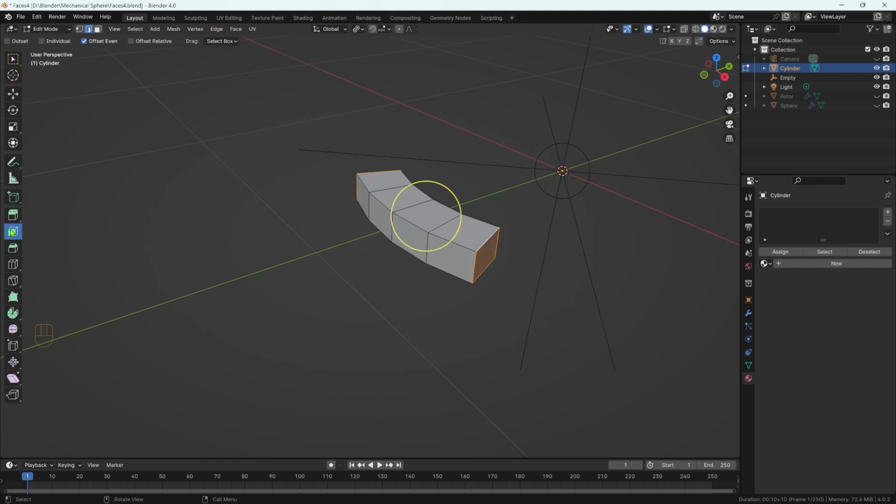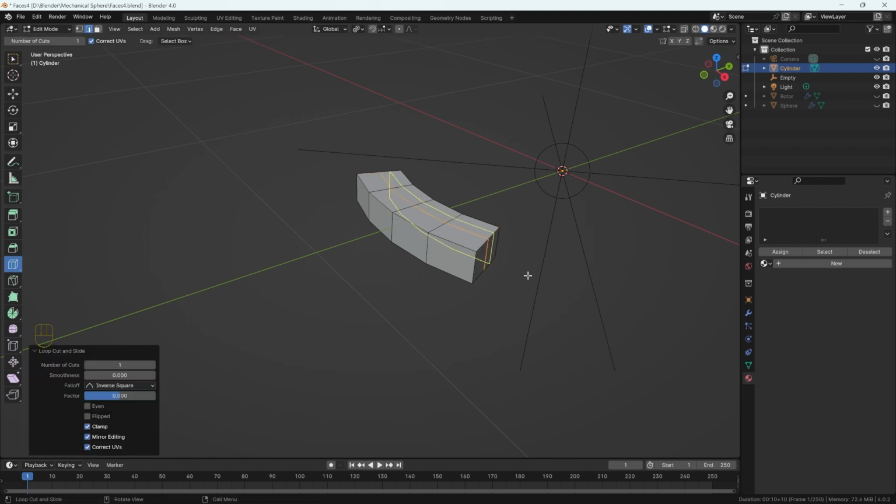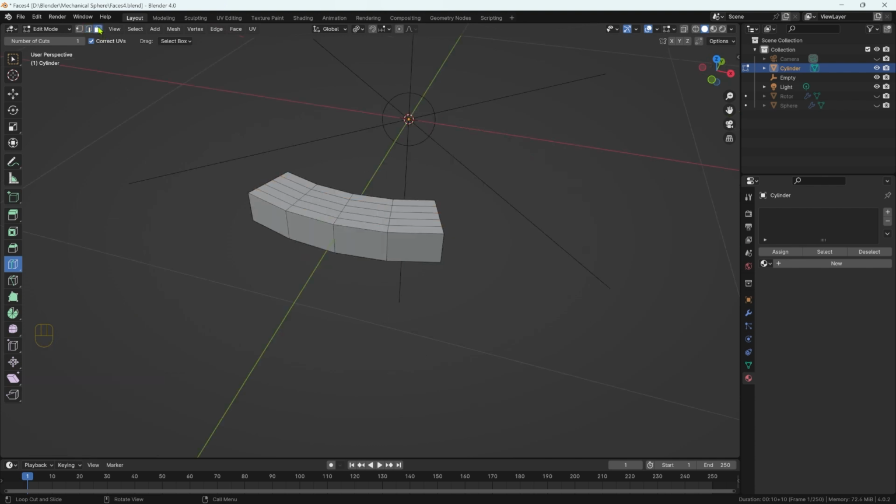So then let's come out of Insert Faces mode and select the Loop Cut tool again. And what I want to do is click here on the top and then let's add some more cuts. So I think I want to go with 4 like that. So then let's come to Faces mode and let's use the Selection tool. So I'm going to select this face and Control select that one. I'm going to hold down the Shift key and select that one and then Control select that one.